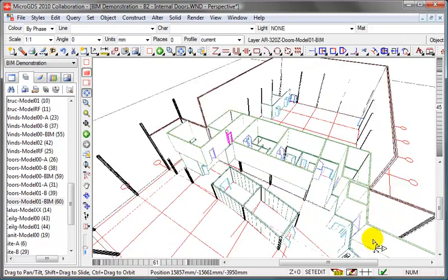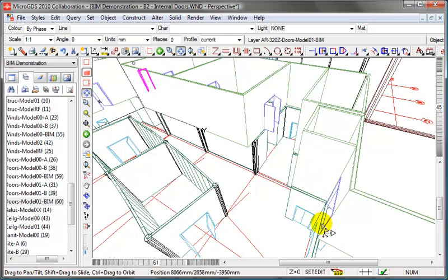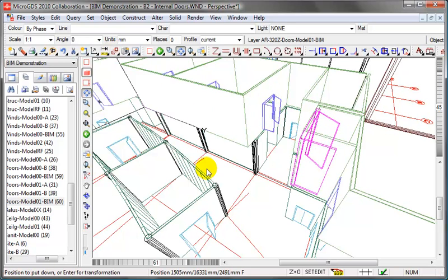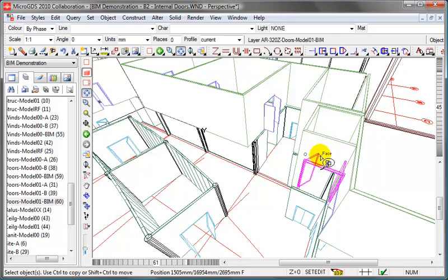And the one final one we need, of course, is the door into the lift shaft. Now again, we can either copy an existing door and edit it, or we can create a new one from scratch. But let's copy this one here. I think that's probably a reasonable one to work with. Just place it in the wall, and let's edit the properties.